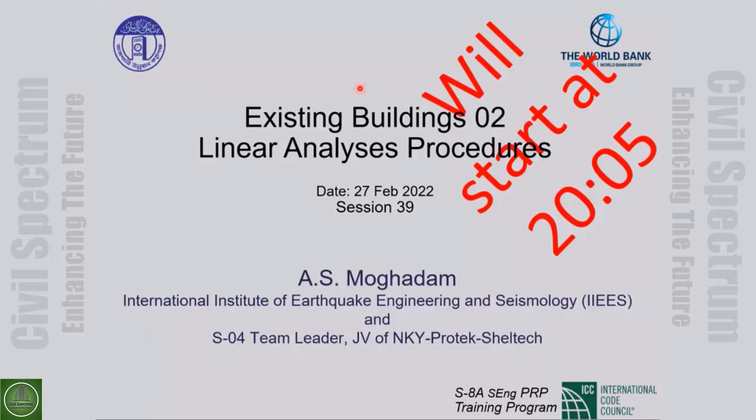For the ordinary loads, we design for strength. Of course, we check for the stiffness, but we design for strength. And in seismic design, we design for damage, we design for ductility. Ductility is damage.